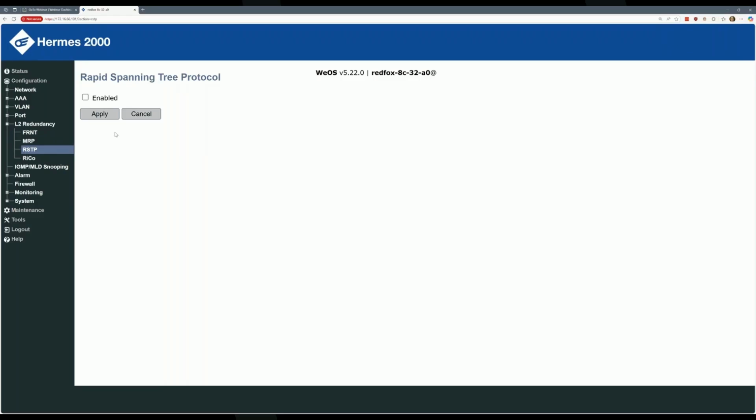So in 61850, there's station bus and process bus, and one of those is carrying a ton of metering data, and you wouldn't necessarily want GOOSE sharing anything with that, because GOOSE carries your protection. You wouldn't want your protection to live in that fire hose of metering data. You would have to separate those. And there are ways to do it. I'm not going to show this right now, but yes, VLAN IDs are important.